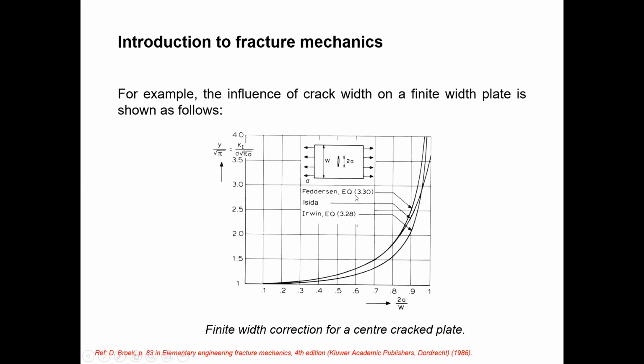This is the center crack plate. This is a kind of modeling. With simulation and some practical data, they find out models to predict something, so you can get a rough idea of the crack. With this model you can get a rough idea. When you change the crack length, that Y value varies. Even though these three models have different curves, all three curves give the same meaning.